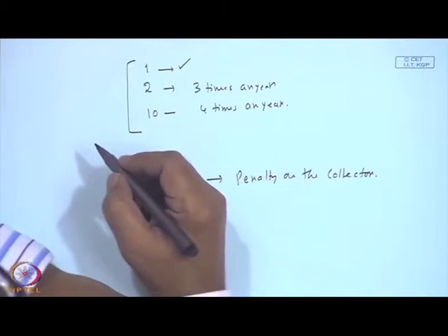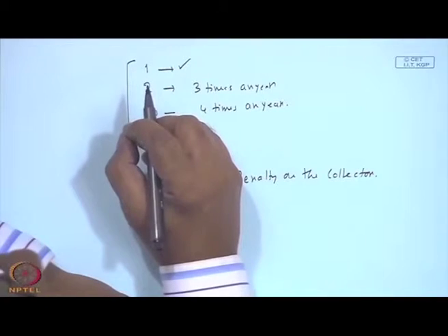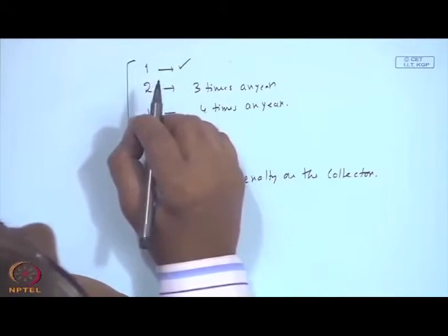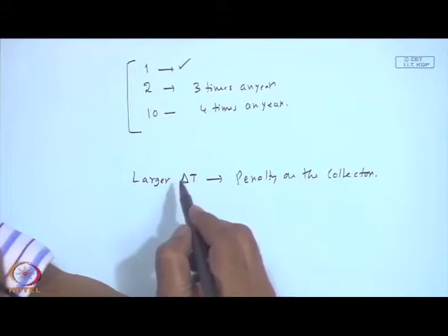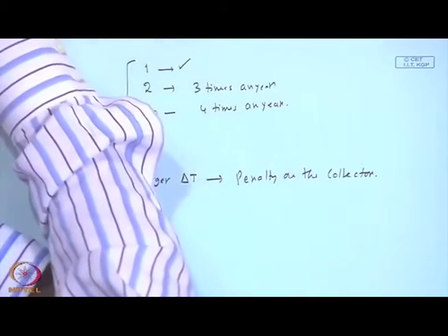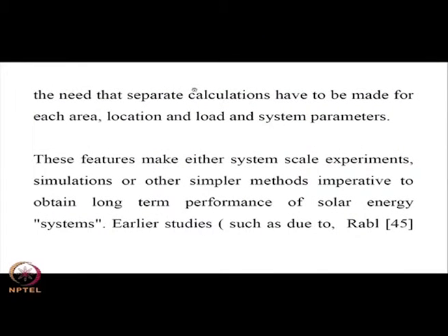So, you are asking the solar collector to deliver energy at a much higher temperature if the load heat exchanger is poor, and hence the collector will be operating at a lower efficiency, and hence you have a higher curve or a lower load fraction met by that particular system.